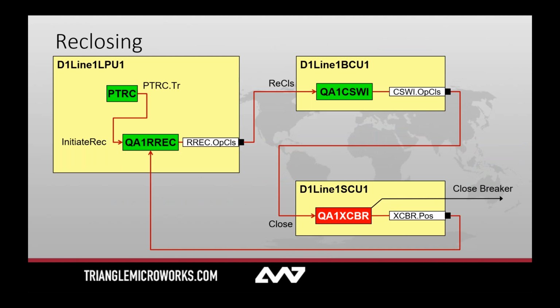So now let's talk briefly about logical node communication. This is a simplified version of the recloser function that we'll be displaying today. Each of the yellow boxes are IEDs, and the lines completely contained within the boxes are the internal signals, while the lines between the boxes are the GOOSE messages. The arrow indicates which direction the signal travels from logical node to logical node. Later on, Jim will be showing how the signal flow display in Test Suite Pro is used to monitor this communication.